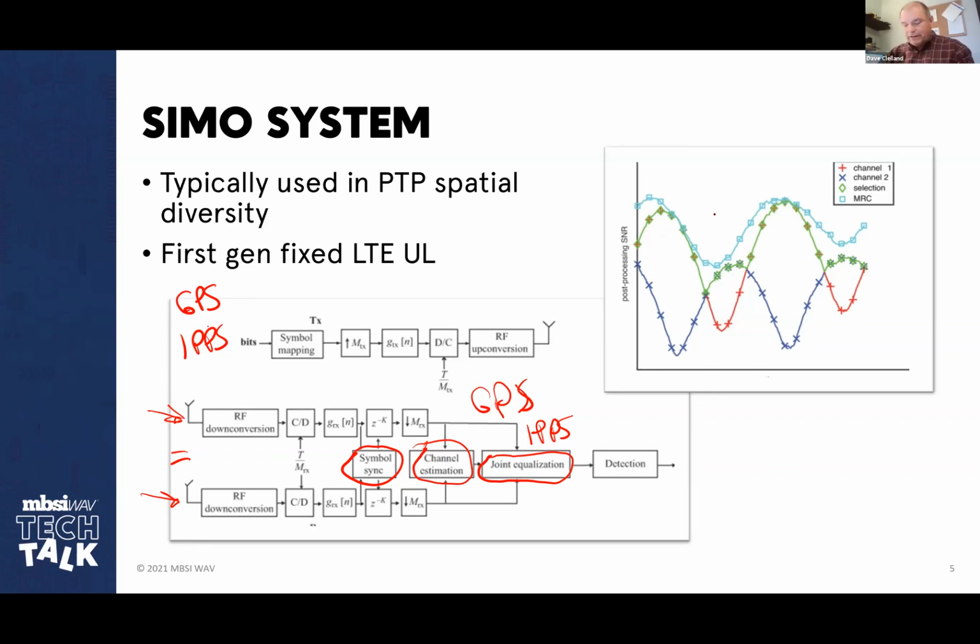So in this particular case, the real important thing here is that there has to be synchronization and calibration between the transmitter and the receiver. We'll talk about this calibration business in a minute as we move along in MIMO. But what I wanted to show here was that the point of MIMO is not to increase the signal strength, but to decrease the amount of fade margin that we have to apply. We'll watch this in a minute. Okay.